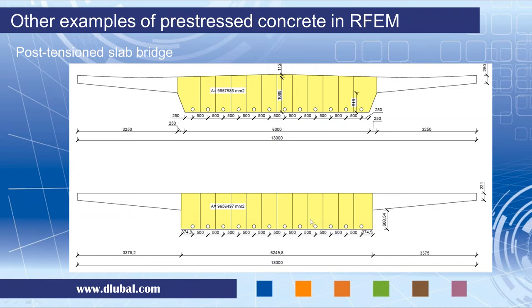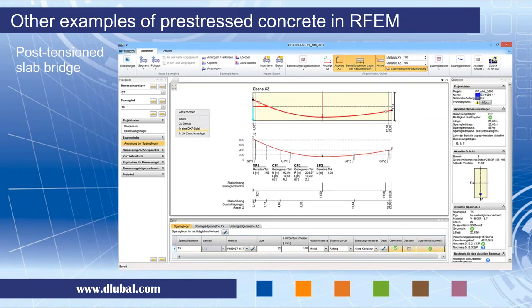Via these result beams we can design each strip of the slab separately. Of course, in each of these result beams we defined such tendons.